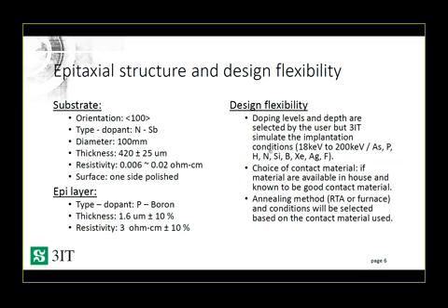Usually for silicon, we use aluminum and aluminum silicon. If for some reason, for process compatibility after we make these, this is not a good material selection, then we can change the metal contacts. This being said, we need to make sure first that we can deposit the material in-house, and that we've actually tested in the past this metal on silicon and know for a fact that it is a good contact. And afterwards, for the annealing method, we have a rapid thermal annealing system or a furnace.